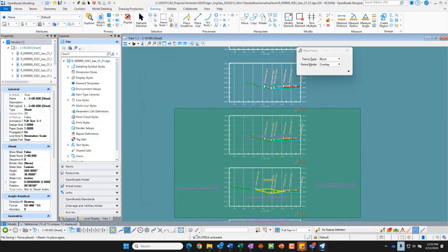If I had that issue, the person who can fix the ground line display is the owner of the existing terrain. So that's going to be your surveyor. I have scoured my data and updated it. My data is pretty old, but I updated it to my current standards. I updated the templates and the Open Road standards. Yes, your surveyor could do that, but sometimes updating standards will revisit observations and they don't want to change their terrain. So it would do more than just change the symbology.